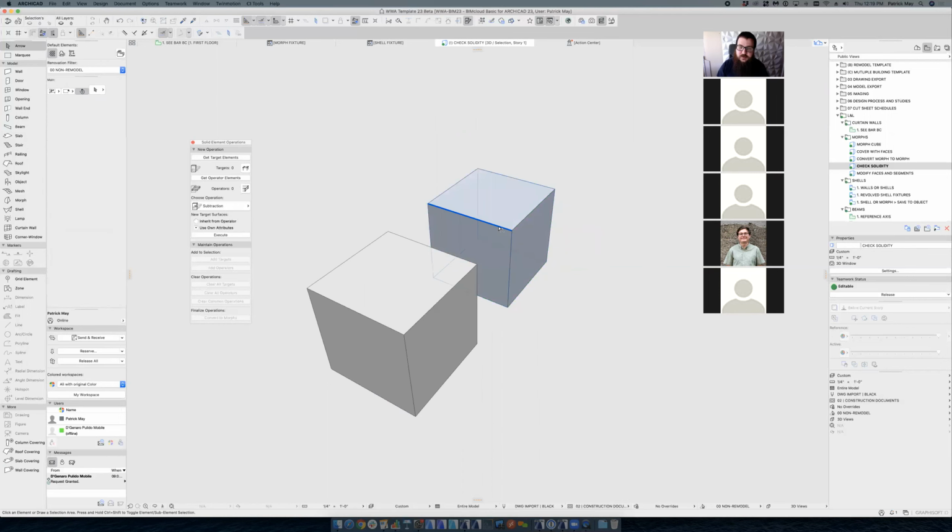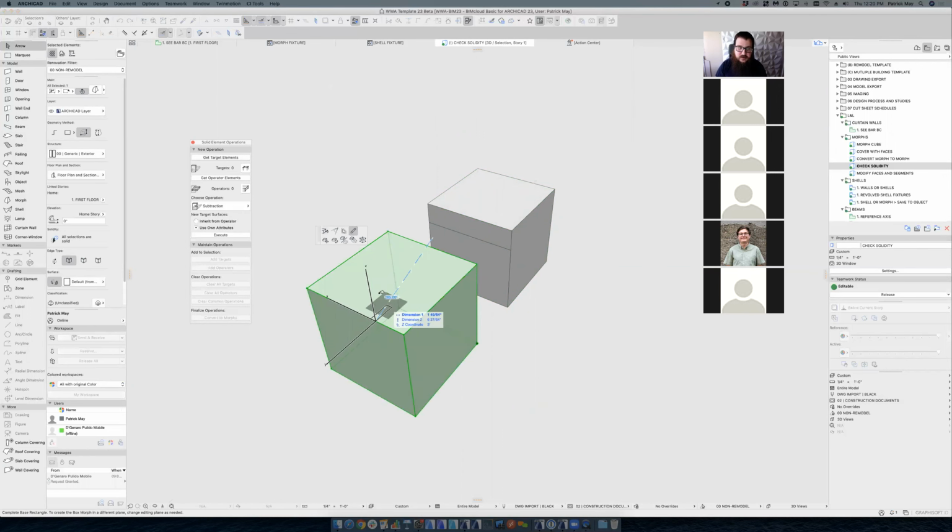It's usually when you start grabbing individual edges and copying those down and pushing and pulling and getting those sort of micro reveals that you start ending up with non-solid morphs. And it can be something as simple as what we saw there with just a little line that didn't get copied, or a fragment of something that's on there. And tracking down all those little details that need to get purged is really tedious.